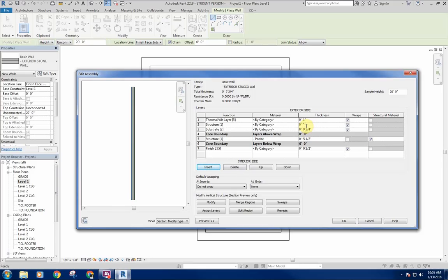So I've got 1 inch there, and then I'm going to put that on top of another inch of some exterior insulation just to help a little bit. It won't go all the way down through the stone layer, but that'll at least help a little bit. And it'll also give us a subsurface to put our stucco on. Not something that you would typically do, but any insulation can help. It'll also give us a little bit better offset for our sill, because our other walls are like 11.5, something like that. So we don't want that offset to be too enormous there for a sill.